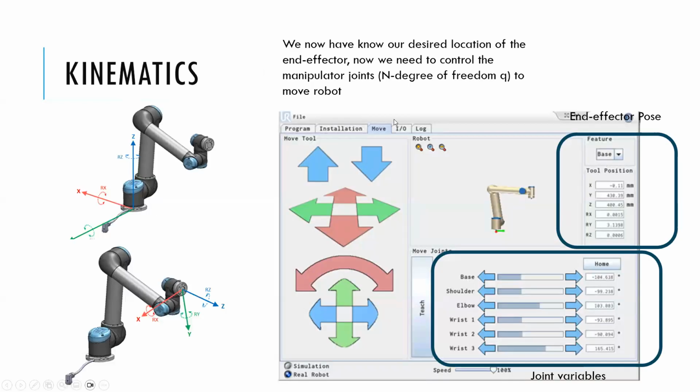So we're going to be using at least the UR and the FANUC system, and then if we have time, I'm also going to bring in the ABB, which works very similar to the UR. The UR is my preferred one for getting started. It's also easier to interact with, like some software interfaces as well. There's a lot of Python interaction with it, or you can program it on there, and the programming is more block-based. You can just drag something on there and click and go. And the FANUC is more of an industrial system, and it has its own language there. It's more C-like, and it has a richer programming language.